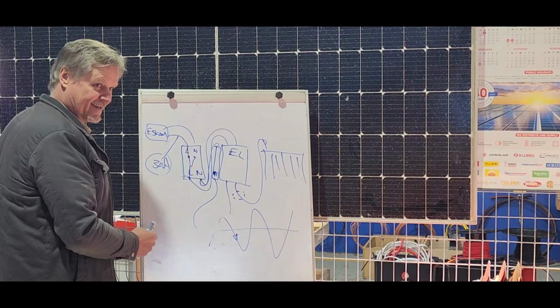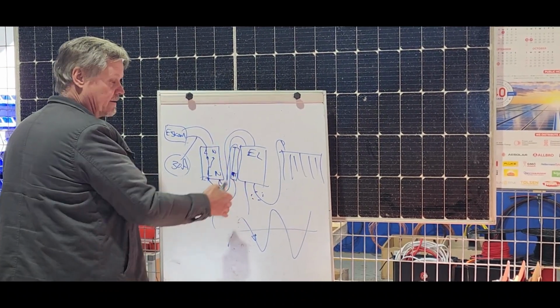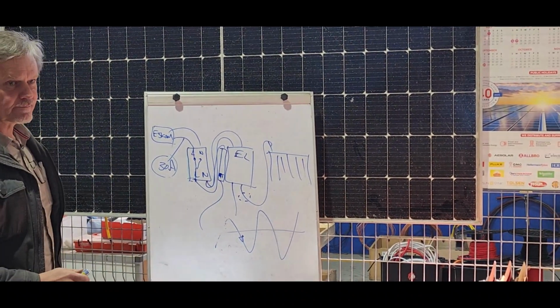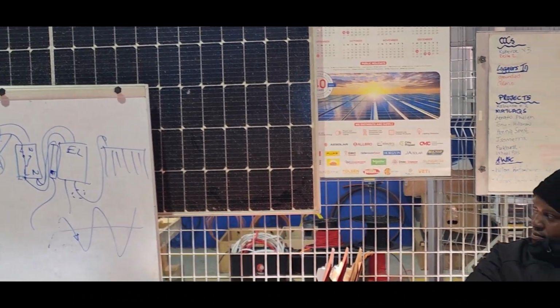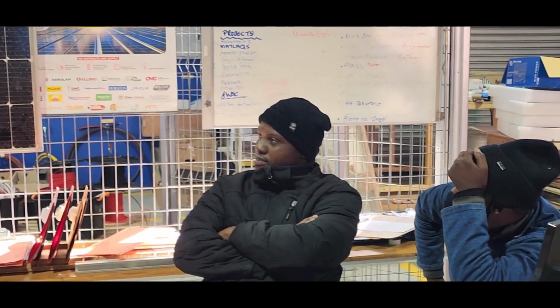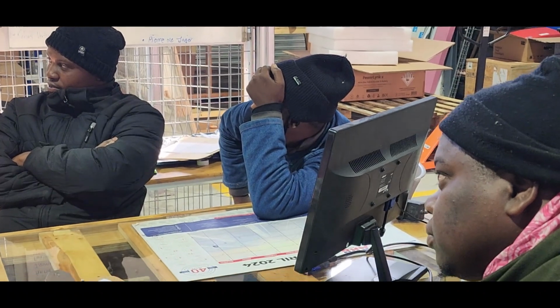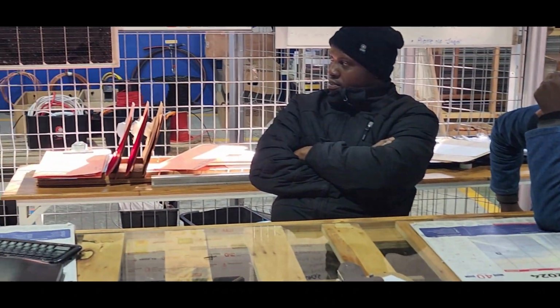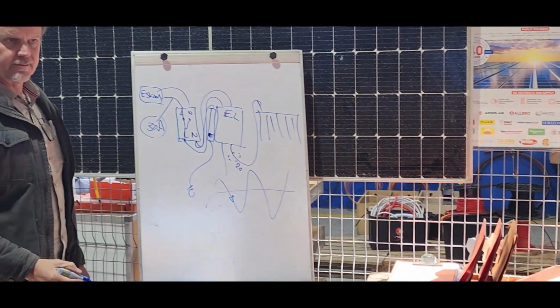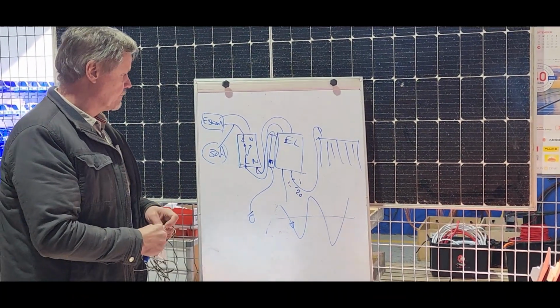My reason is because the stove is before, so meaning there might be some amps on this side. Absolutely right. So the stove would be using 10 amps, and then the rest, 20 amps, is running over there. So have a clear mind.